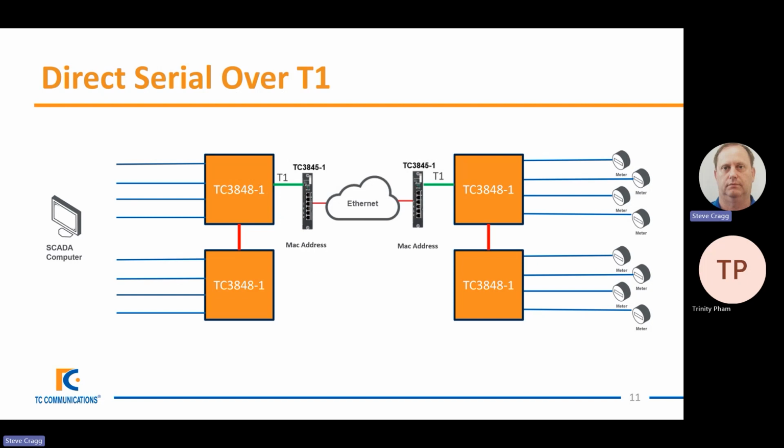Normally our jumbo switch products are connected using IP addresses for the devices. They asked, again to eliminate any need to go through any NERC CIP compliance, for this to be connected using MAC addresses.